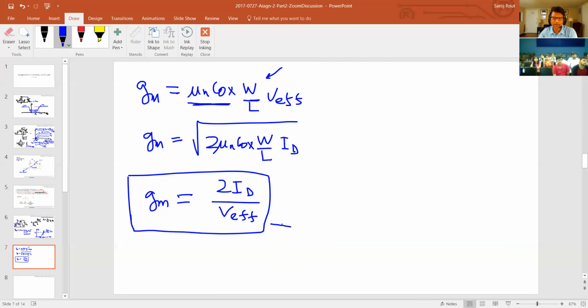But this is probably one of the most important, at least I find it the most useful expression while you're designing, because in your design, mostly when you start doing analog design, you'll see that usually a current is given to you. You never design with voltage sources. Your biases are always through currents. The reason is that if you do it with voltages, your currents will change dramatically over process, temperature and so on. So what you do is you generate fixed currents, and we'll actually create a project to generate a bandgap and current, which is one of the key elements in pretty much any analog chip.